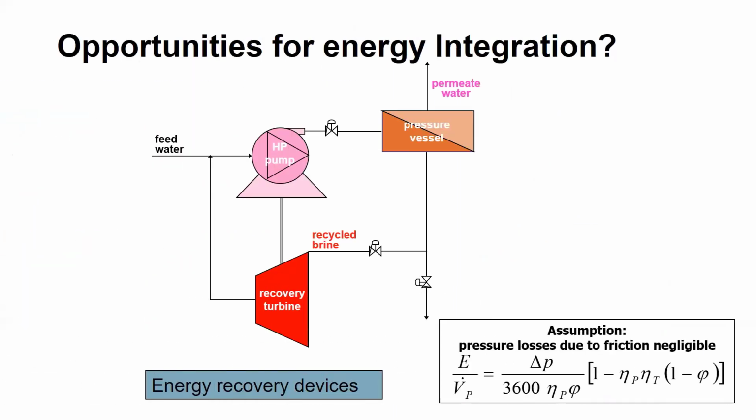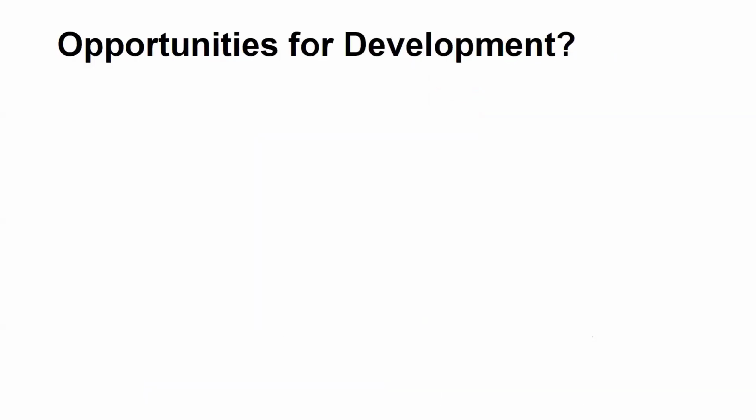So one of the areas of energy integration opportunity in order to improve the cost efficiency of the RO process as it is implemented in the mining sector, I thought, would be, for example, energy recovery from the high pressure brine coming from the membrane toward the low pressure feed water. So there is a potential there, and most of the research is done, as Prof. Majosi and Prof. Roger indicated, and I think it's a good opportunity. I'm not sure how much work on energy integration within the RO process as it's integrated in the mining sector has been done to find any opportunity for energy recovery. But I think it's an area worth exploring so that we can improve the cost efficiency of the process.